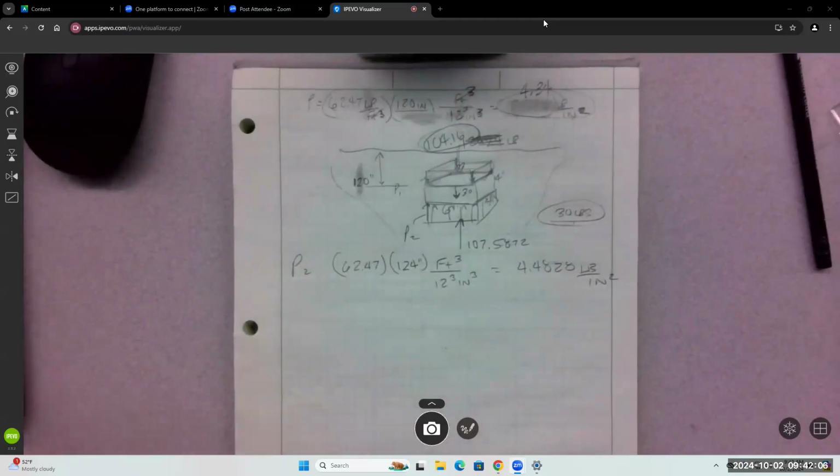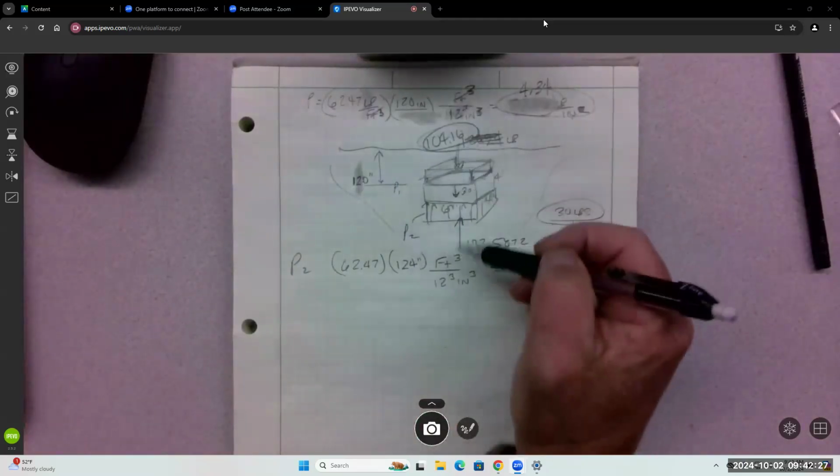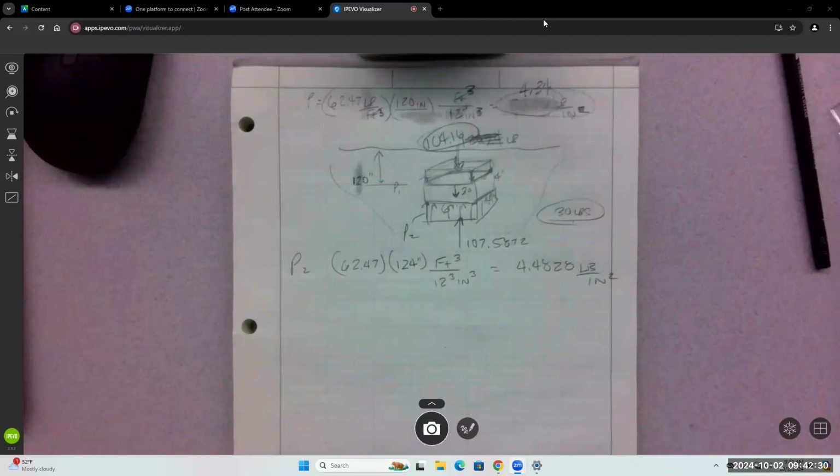Equilibrium tells us what? Is it going to sink or float? It's going to sink. We have a buoyancy force of how much? Like 3.43. Okay, that's our buoyancy force. The difference between the top and the bottom is your buoyant force. If the object weighs 30 pounds, the buoyant force is 3. It's going to sink, not just slowly, it's going to sink fast. An anchor. Buoyancy, that's how we do it, right?